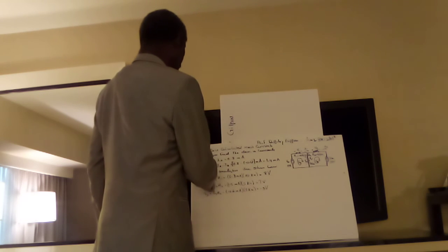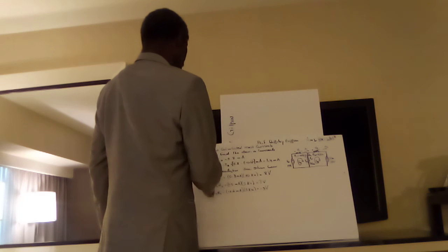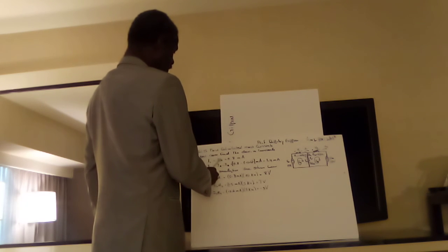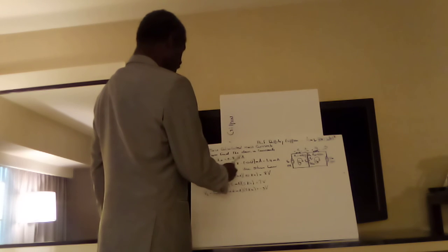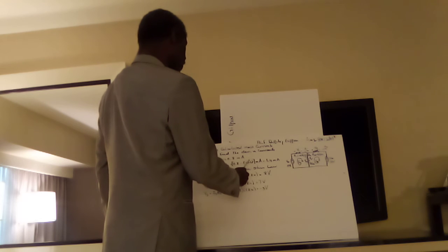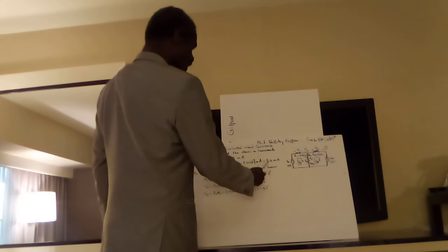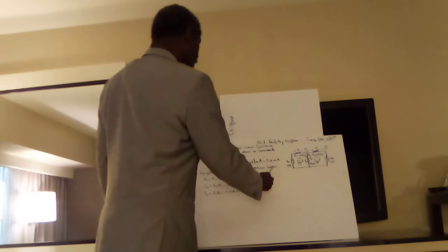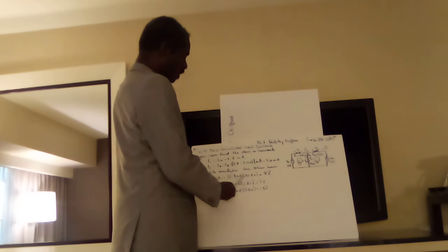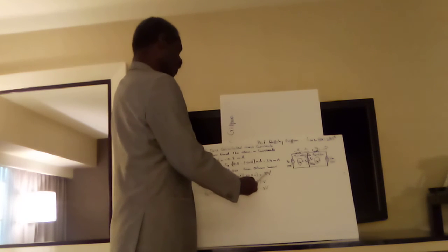So as we continue, with this calculated mesh current, you can now find the device current. And we have now that I1 is equal to IA equal to 0.8 milliamps, and I2 is equal to IA minus IB equal to 0.8 minus minus 0.6 milliamps, that's equal to 1.4 milliamps. And to complete the analysis, we use Ohm's law and say that V1 is equal to I1 R1, that's equal to 0.8 milliamps times 10 kilo ohms, that's equal to 8 volts.